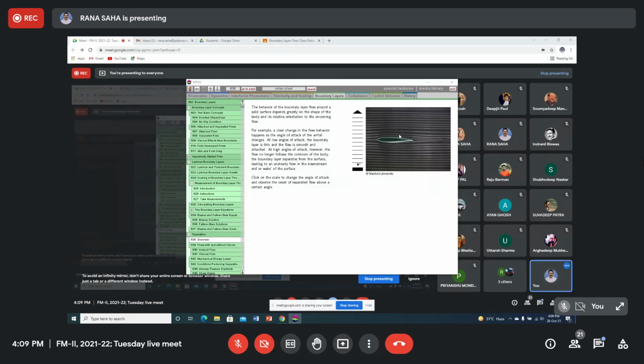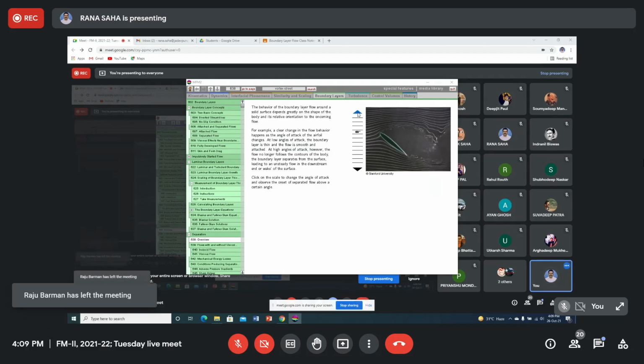So the first part of our study, that is the wall shear stress, will be, along with that, this area will be increased, and you have more skin friction drag but minimum form drag. So this is what I was trying to communicate to you: a trade-off or optimization is required to get the minimum total drag. Actually, it is the total drag that is of our concern.